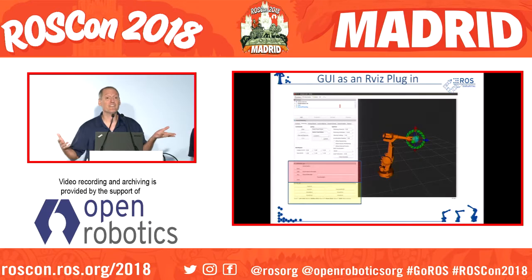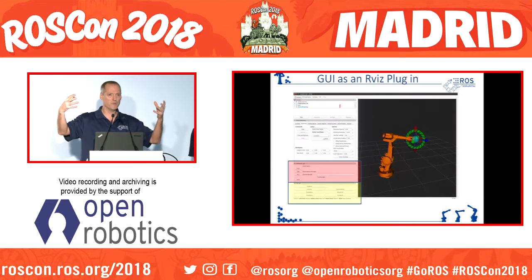So to make it even easier, we've now added GUIs in that same GUI that I talked about before in RViz, where you can just click on the buttons and have it say, take a new observation. So now you can use MoveIt to move the robot around, and then just click, oh, take another picture right here. This is a good one. And you can then display your images, and it will show you that you've got a good observation, and then you can finally run it and then save the results, and it will move the transforms around, and everything's good.